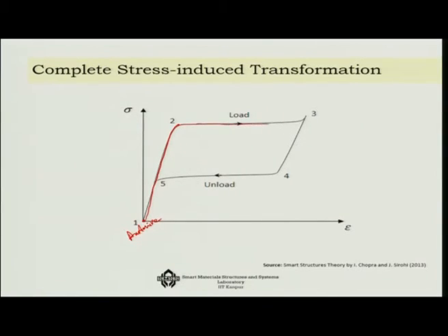This is stress induced phase transformation, and I am going back to the martensite phase, and then from that phase I am reducing the load again, and initially it is once again elastic, and then the huge change, and it comes back to number 5, and if you further reduce it, it will be at that austenite stage itself.